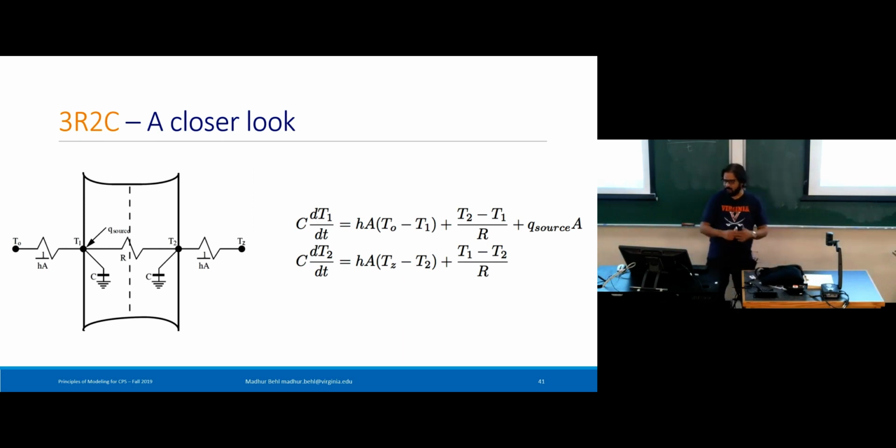Today we'll wrap up the discussion that I started in the previous lecture, and all of this is related to the fact that we are building our first model with the goal of predicting the zone temperature in a space. And we established that we are not really interested in modeling all of the HVAC equipment, but we abstract its operation in just one single term, which is the heat flow in the forced air HVAC component. What we are interested in modeling is the system itself, the zone, and its physical boundary or the building envelope, and how the heat flows into and out of this building envelope.